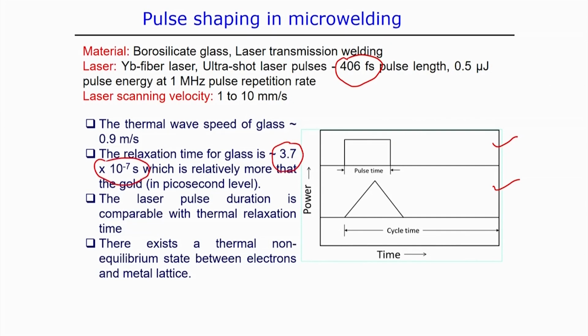So, when the relaxation time is more as compared to the pulse duration, it is a better option to analyze this phenomenon using the non-Fourier effect of the heat transfer mechanism. This mechanism is based on the existence of a non-equilibrium state with the application of the femtosecond level pulse on the substrate material.